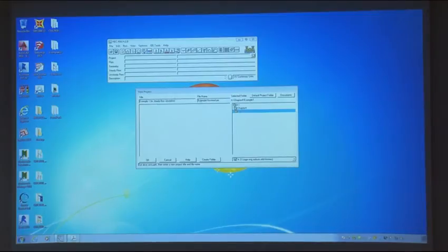Then they have the file name, and you can make it short. They make it pretty long. So for example 1 and steady state, I can just delete some extra characters. So my file name for the project is just example1.prj. That's the highest level, as a project, so it always has the extension .prj, okay? Then I'll select OK.